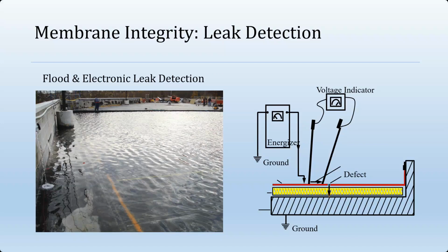We block all the drains and scuppers and fill it with 2 inches of water, let it sit for 24 hours, have the manufacturer's rep come back and then examine and sign off on it. But if there are any leaks in a flood test, the leak can propose some water. And once that water gets on the underside, it can traverse laterally in any number of directions. And it's going to be a lot more difficult and more time consuming to find that leak, that breach.